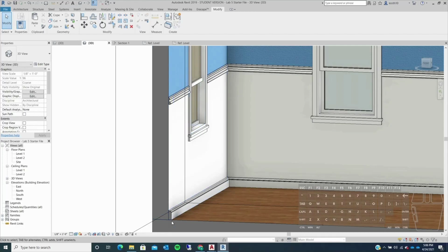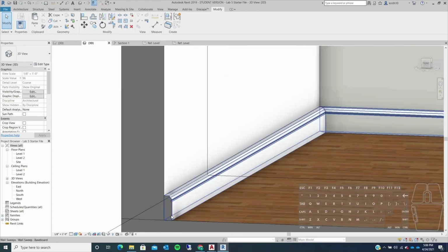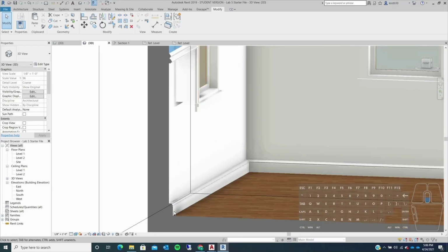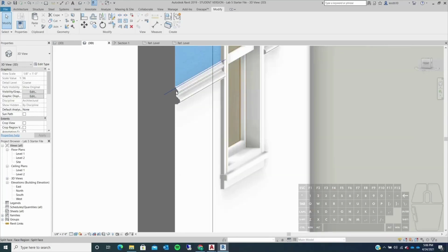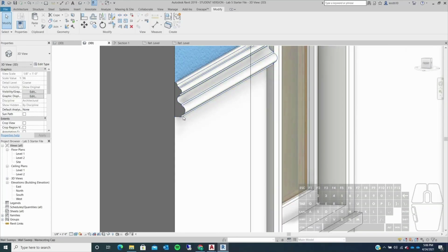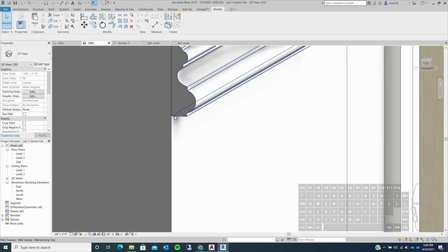So you would have this entire panel. Then over top of that, you would be putting all your different moldings. So you'd be putting the baseboard at the bottom, then all the rails, and then your cap at the top. And that would just be basically sitting on top of it. And you would have a little bit of thickness here. So like 3/4 of an inch, it would be sticking out here, all right?